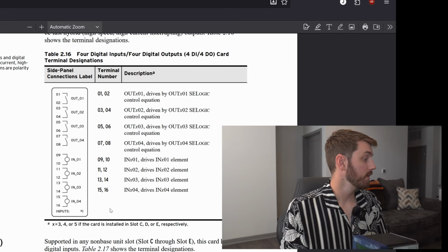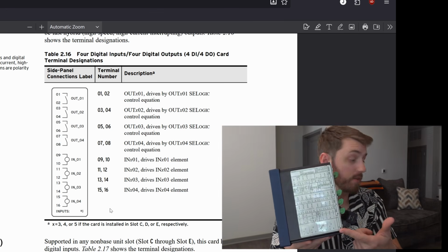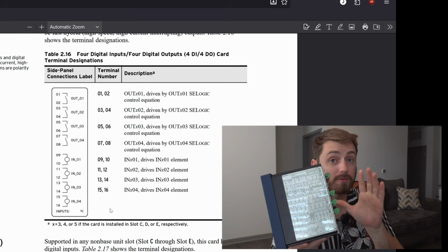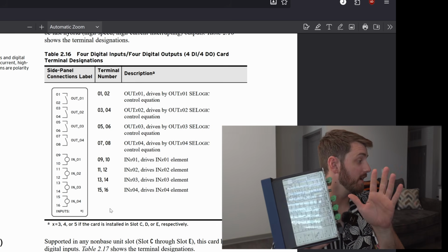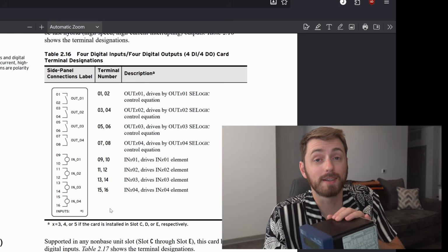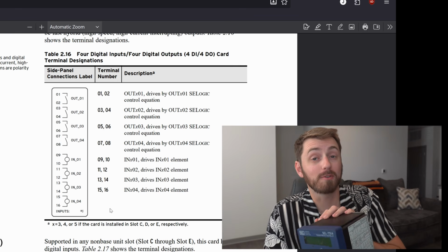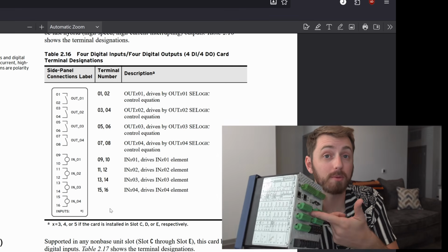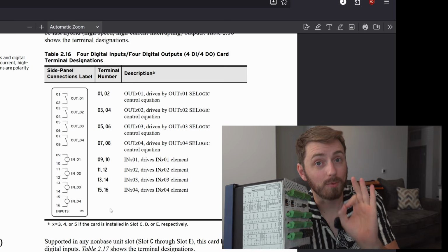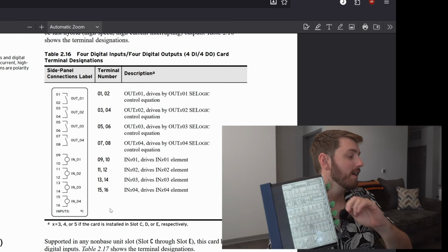The last thing I want to note for these SEL relays, the terminal names mess people up all the time. One notable time I saw that actually made an entire power plant go dark for a few hours because someone installed a jumper in the wrong place. We've got to really pay attention to how these work.